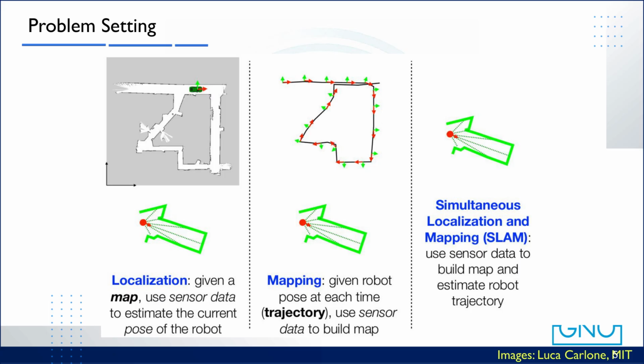The conceptual breakthrough in SLAM came from realizing that when mapping and localization are formulated as a single estimation problem, the system actually converges. Even more interesting is the fact that landmark correlations, something many early researchers tried to minimize, are actually the critical component of the solution. The stronger the correlations become, the better the overall estimation.